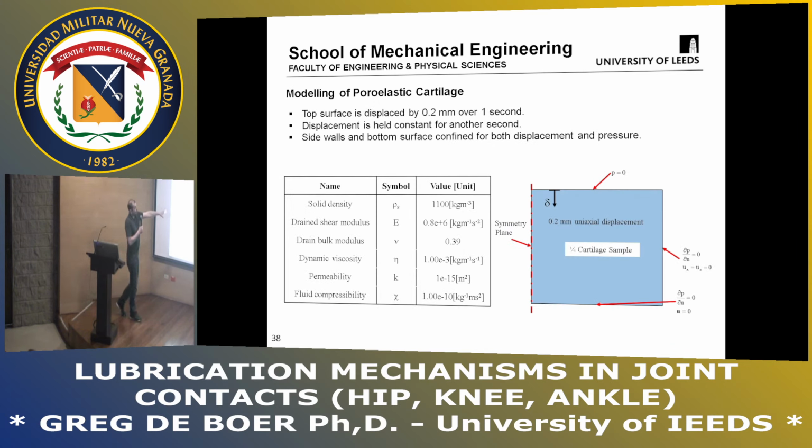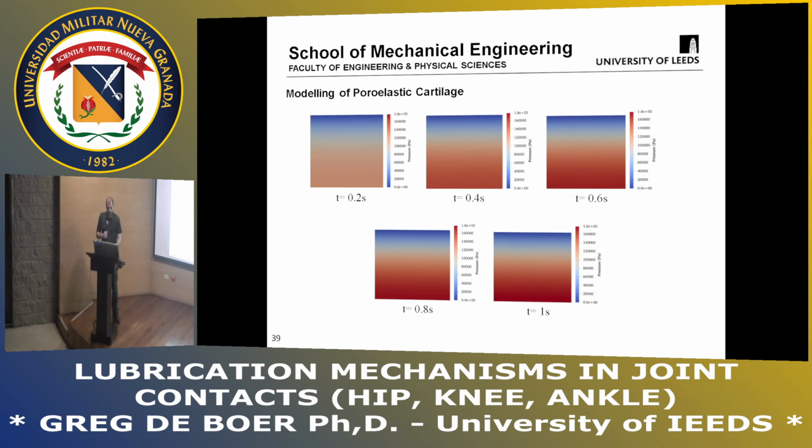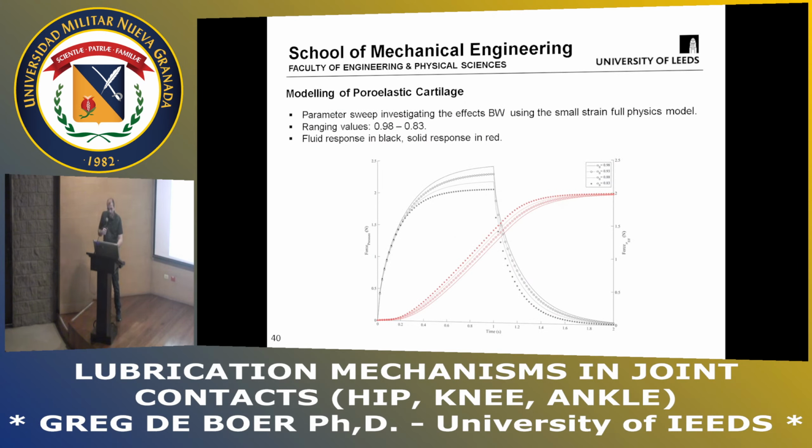Again, we set this problem up. We're just going to compress the top of it, and we stop flow from leaving this material elsewhere. We use very similar material parameters to the other model well established in the literature. So you can see here, it's the time-dependent model. We get this pressurization of the material over time. But really, this is the most important outcome. What this shows is that if you add these extra terms, you get significantly different values of the total force that's applied in a given time period.